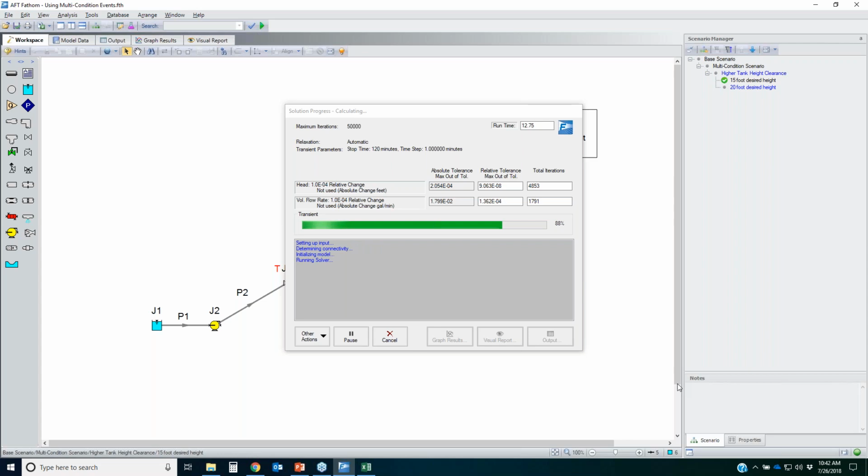With my time step being every minute, when you're transitioning from one time step to another, going minute to minute, that might be enough time for your whole system to come to a new steady state. That's what XTS does: it captures a whole picture of steady state simulations over time. As long as your system is changing very slowly and given enough time for those water hammer waves to dampen out, then XTS will give you a very good picture of what's going to happen.